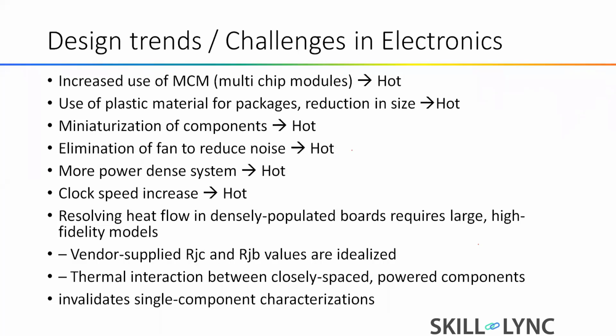Resolving heat flows in densely populated boards requires large and high-fidelity models, and that again became a challenge because we have to depend on a lot of network models. In future lectures you will see what this network model means, and also we have to be very sure about the vendor which supplies these thermal resistance values. Again, in the next few slides I will introduce you to thermal resistances, and then we'll talk more on this.